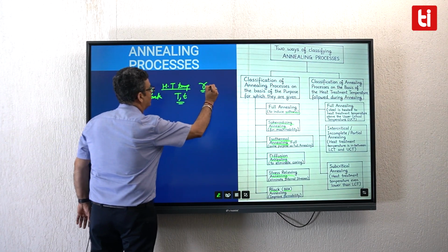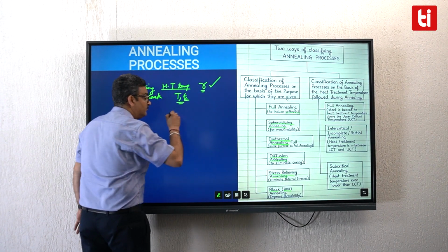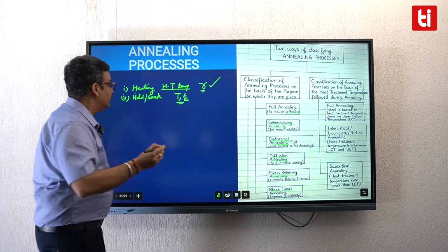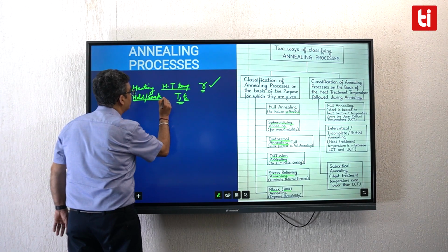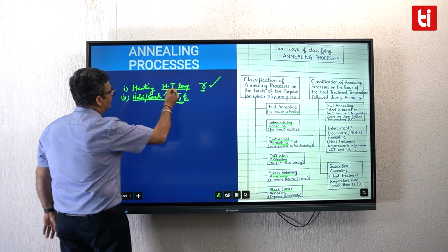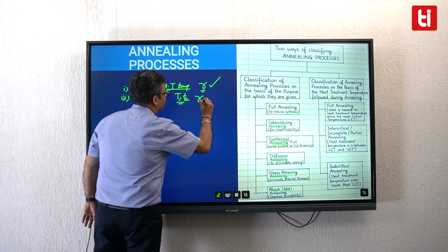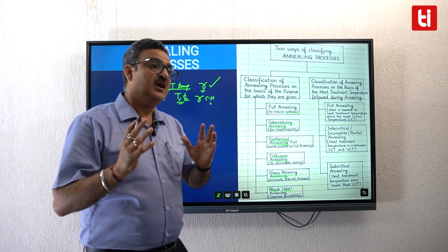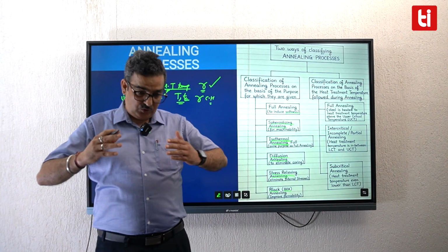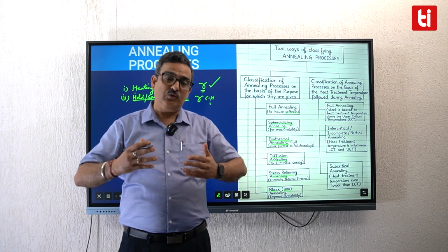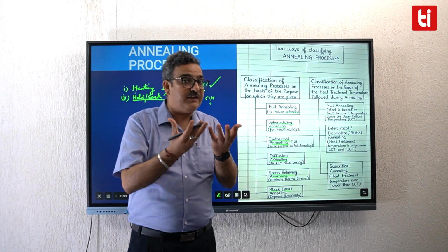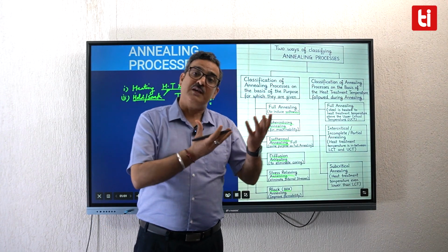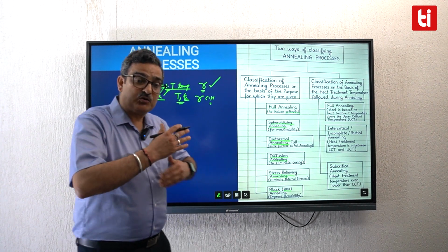So temperature you have already given in the first step, but diffusion needs more time at the high temperature to get completed. So you provide that holding or soaking at the heat treatment temperature and diffusion gets completed, so this austenite becomes chemically homogeneous. Now you have that austenite with you, which is ready to get transformed, which is ready to get decomposed into the product phases which you wish to see in the final microstructure of the steel under room temperature conditions. So you will now cool your steel.